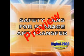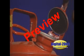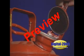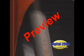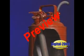Safety cans for storage and transfer. Approved container of not more than 5-gallon capacity. Spring closing lid and spout cover. Safely relieves internal pressure when exposed to fire. Flame arrestor screen. A flame arrestor screen prevents fire flashback into a can's contents. Double wire mesh construction with a large surface area provides rapid dissipation of heat from fire so that vapor temperature inside the can remains below the ignition point.